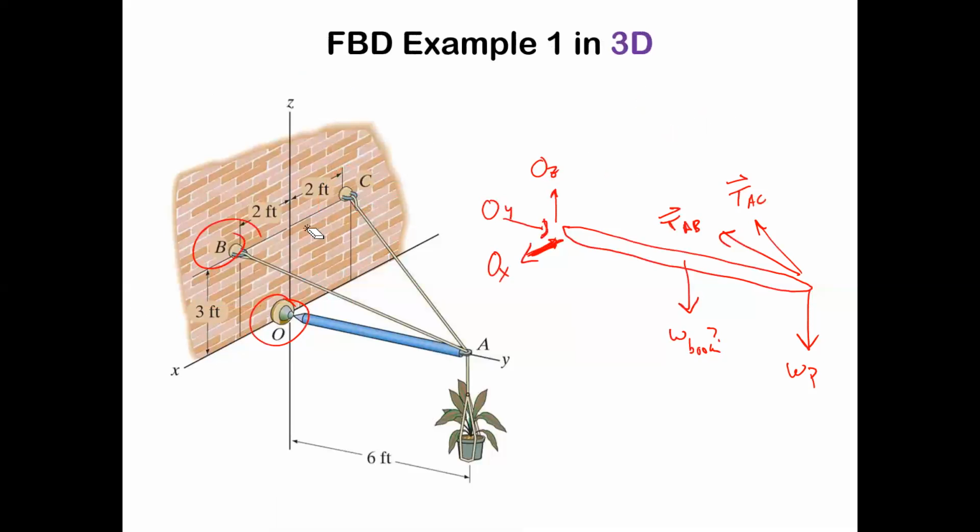Remember, with the free body diagram you're sort of finding the key piece of the puzzle that you remove from the whole system and just put the forces acting on that. So we don't include anything that's not part of that beam, that's not directly attached to that beam. We just ignore it. And that really helps us clarify the problem, right? Because once you pull that beam out and just look at it, it's a lot easier to say, oh yeah, there's just these 5 forces we've got to deal with, right?